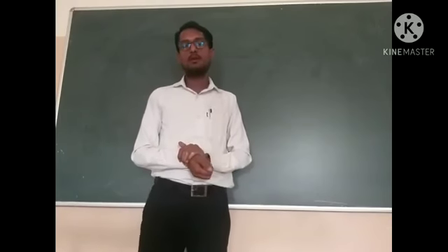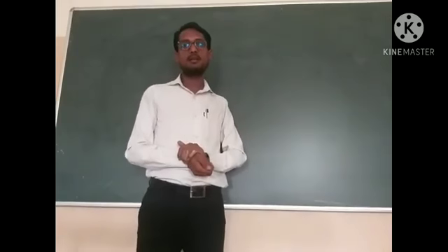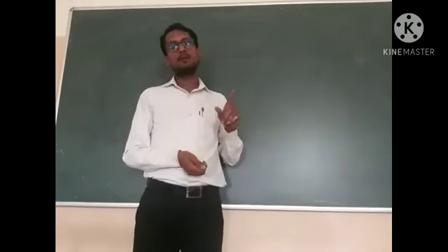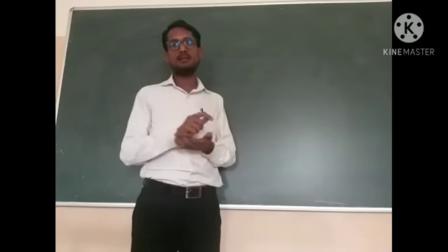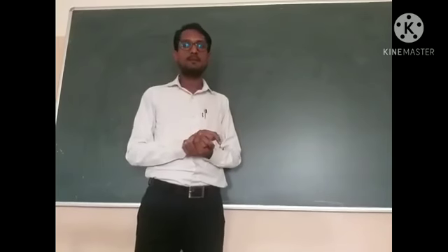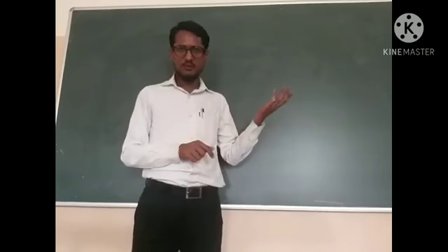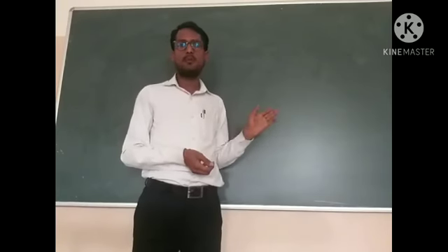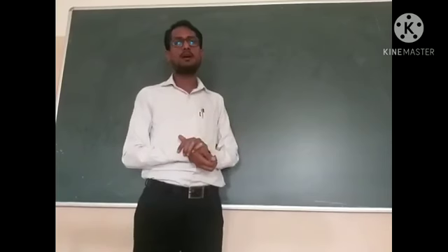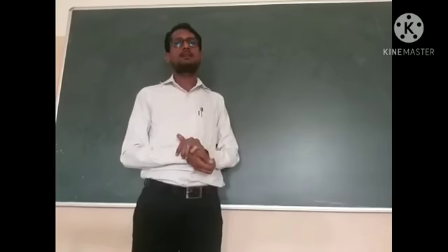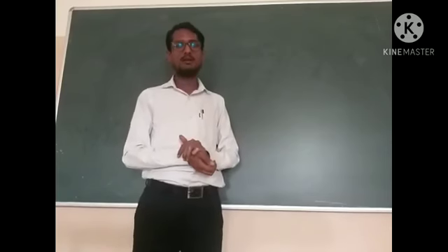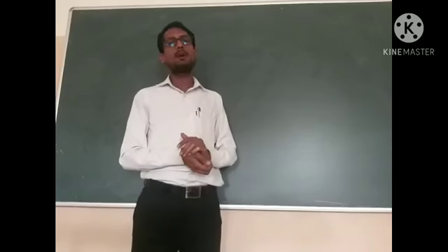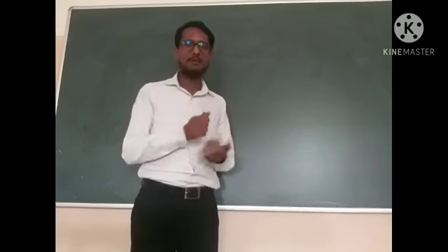In that lecture we discussed the short circuit test and the open circuit test. We briefly discussed the open circuit test. We perform the open circuit test and the short circuit test on a transformer to find out the performance, that is, the regulation and efficiency of the transformer, without applying actual load.